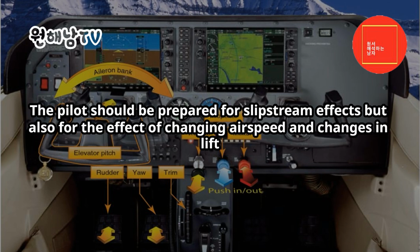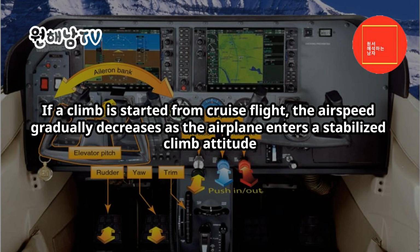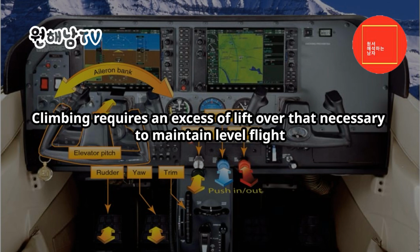The pilot should be prepared for slipstream effects, but also for the effect of changing airspeed and changes in lift. The pilot should be prepared to use the required flight control pressures to achieve the desired pitch attitude. If a climb is started from cruise flight, the airspeed gradually decreases as the airplane enters a stabilized climb attitude. The thrust required to maintain straight and level flight at a given airspeed is not sufficient to maintain the same airspeed in a climb. Increased drag in a climb stems from increased lift demands made upon the wing to increase altitude. Climbing requires an excess of lift over that necessary to maintain level flight.